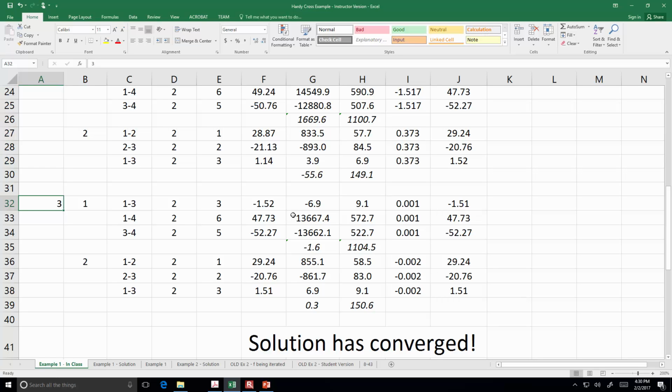And then we're interested in, well, in that case, how much flow is going through each pipe? Because once we know how much flow is going through each pipe, then we can calculate the pressure at each junction and know whether there's enough pressure. People get very irritated when they turn on the shower and it's just a trickle. They like a blast when they're taking a shower. And if they're not getting a good enough blast, that means we have to move the reservoir higher on the hill, or increase the size of our pumps, or change the pipe sizes.